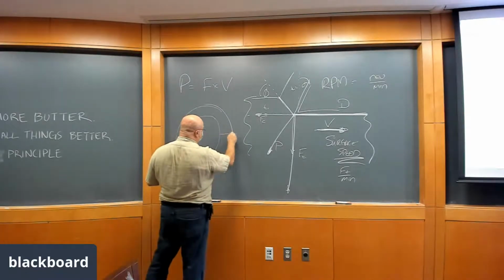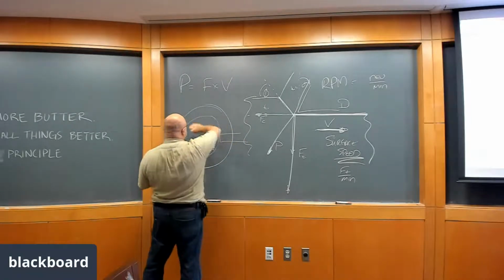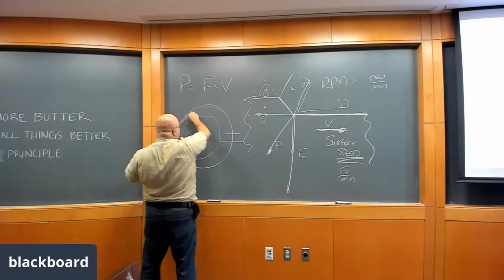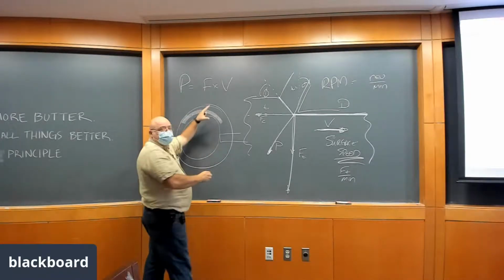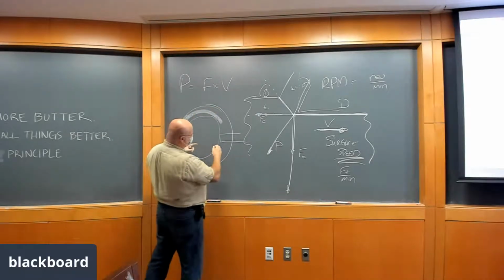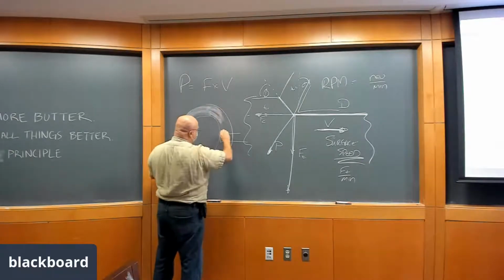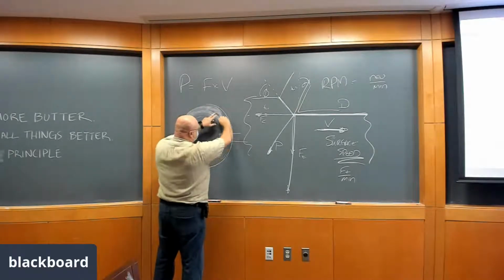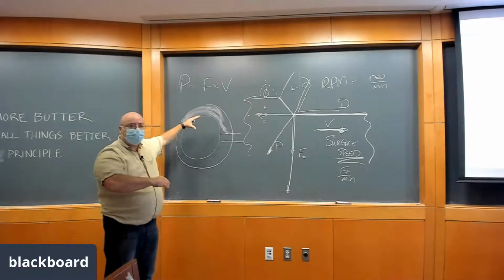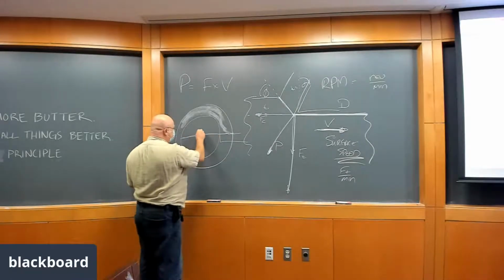And here's our cutting tool. As the workpiece comes around, this part is the uncut chip thickness. It's about to get cut. Is that the width? It's the width of the uncut chip. But that's about to get cut. It's going to hit this, and it's going to flow out on the rake face of the tool right as this happens. So our diameter is coming out like this.